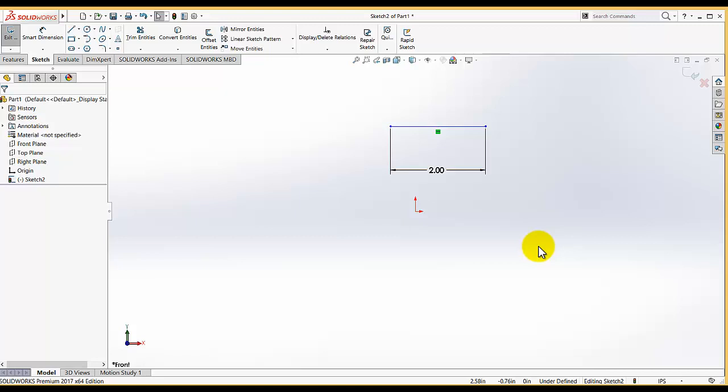In other software we can make the selection of color, and in other software maybe the color will turn into something different, but I am going to talk about SolidWorks. So when you give a dimension or a constraint which fully defines the sketch, then the color of that sketch will turn black, and when the required constraint or dimension is missing, the color will be blue.